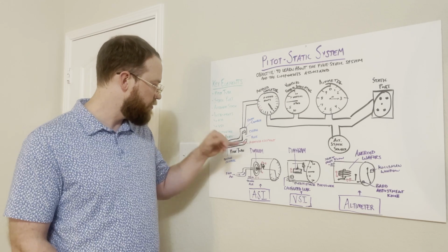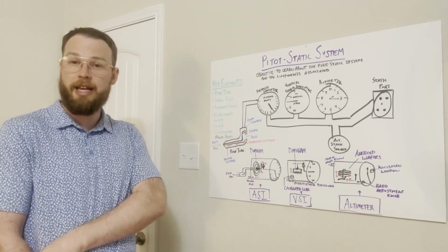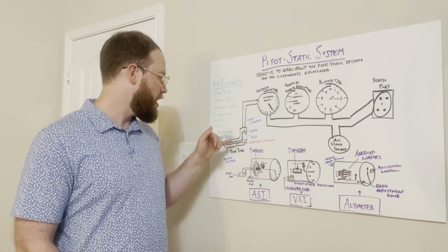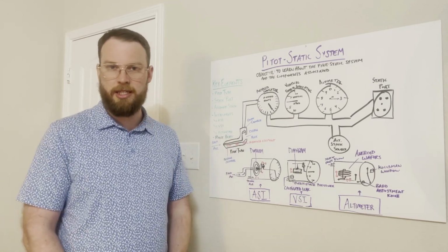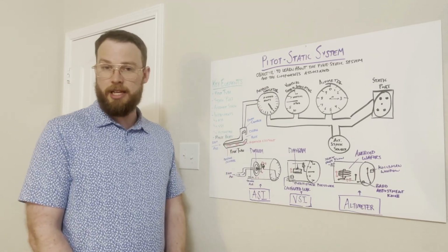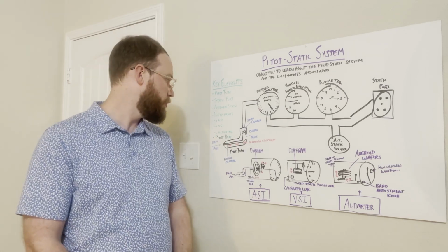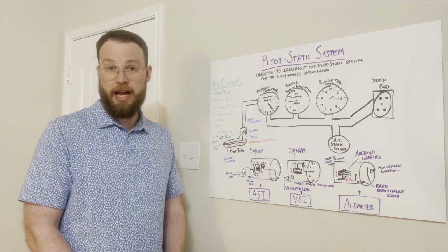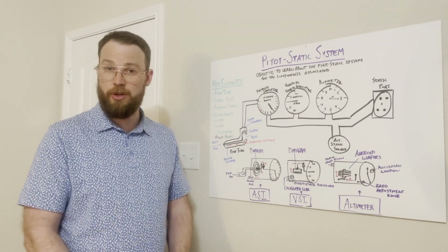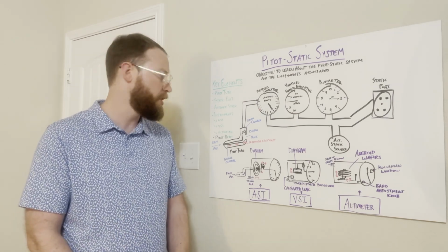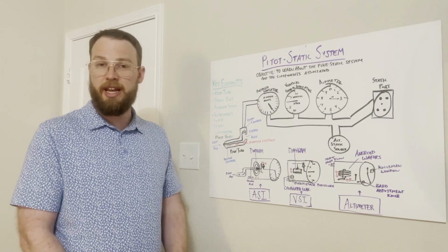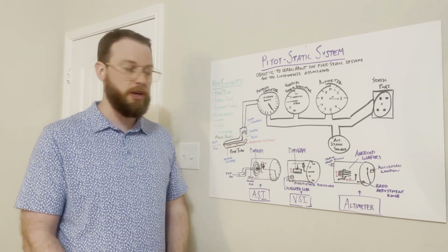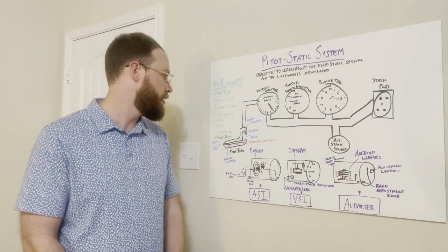And then these little red bars here are illustrating a heating element. Now what that does, basically, as we turn on the pitot heat inside the cockpit, is heat up the entire pitot tube. That can prevent any icing that we may encounter depending on our altitude, or if we're flying through precipitation or anything like that. That can prevent any ice buildup or accumulation on the pitot tube, as well as near the drain hole or the inlet here at the front.